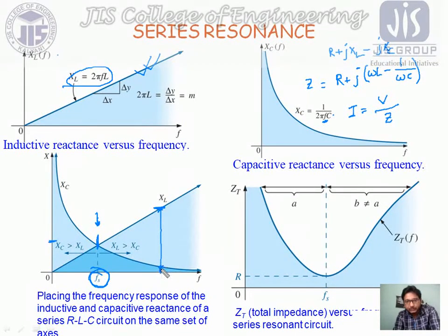So it's clear that for this particular frequency, let's say Fx, the inductive reactance is very much greater than the capacitive reactance. So obviously at this frequency the circuit will have an inductive effect, and the circuit will be lagging.